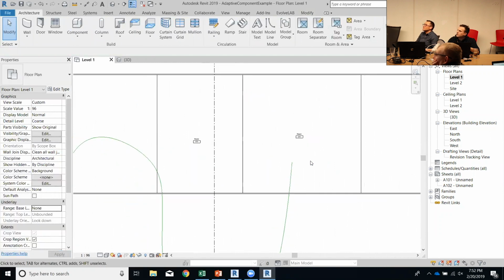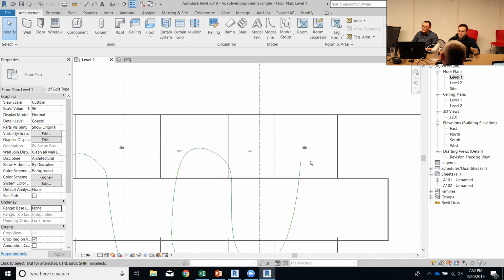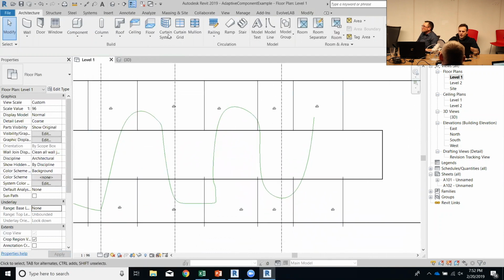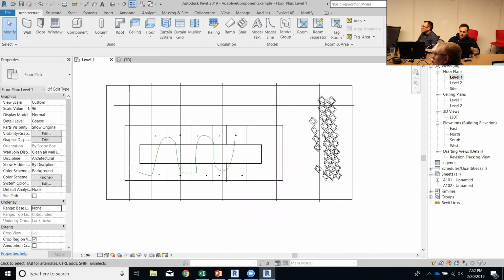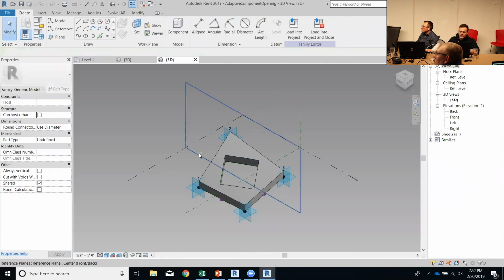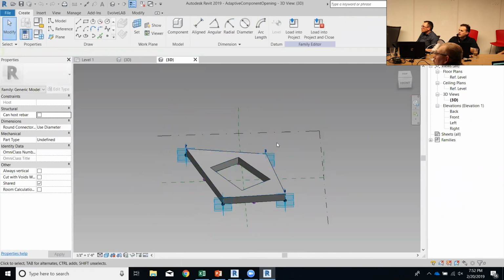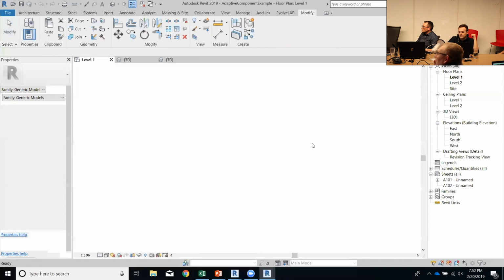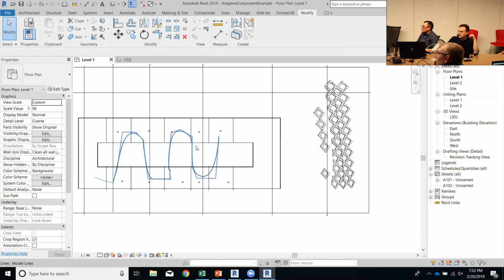So you generated that adaptive component manually in Revit? So we built the adaptive component. I can edit the family itself. And then when you have that adaptive component placed, you load it in the project. In just the same way how we can create a dimension string, you can insert an adaptive component by points. And that allows you to start to manipulate some of this stuff. Again, not the point, though it's very interesting.